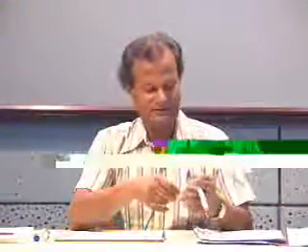Or let's say you want to record the flood situation in Bihar. Then you set up some gauges, and the gauges are not read continuously. It's not that you cannot record continuously, yes you can, but they are very crude things. They are pillars with markings. You must have seen when crossing a railway bridge, there are pillars like this with markings. And what one does is, let's say every month, a reader goes there and records the reading. Then he sends it to a central mechanism for processing this data to be able to forecast what will happen next year, or to link it with what happened in the previous year, so that appropriate flood control mechanisms can be set up.